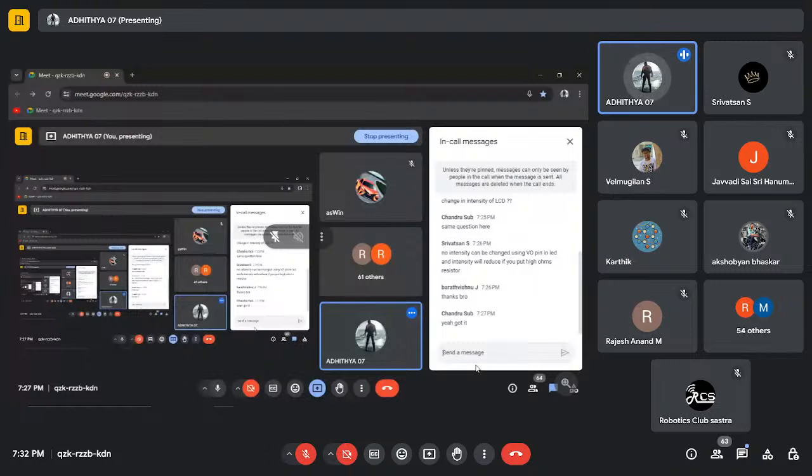And there are 4 grounds here. I'll be explaining why a bit later. Pin number 6 is output 2, so you'll be connecting it to the other end of the motor. One end will be positive, this one will be negative. And then this is input number 2, which when given high, will rotate the motor in a clockwise motion.